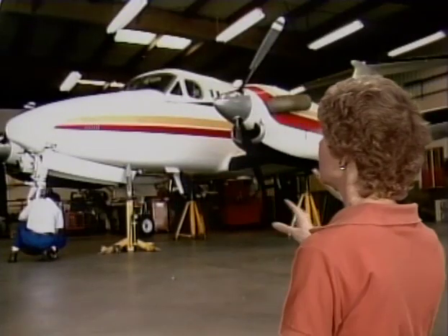Now let's assume you've been doing maintenance on the landing gear retraction system of an aircraft. If there is any possibility that the maintenance may have affected the landing gear's ability to retract or extend properly, it is very important to make an operational check of the landing gear retraction with the aircraft placed on jacks.